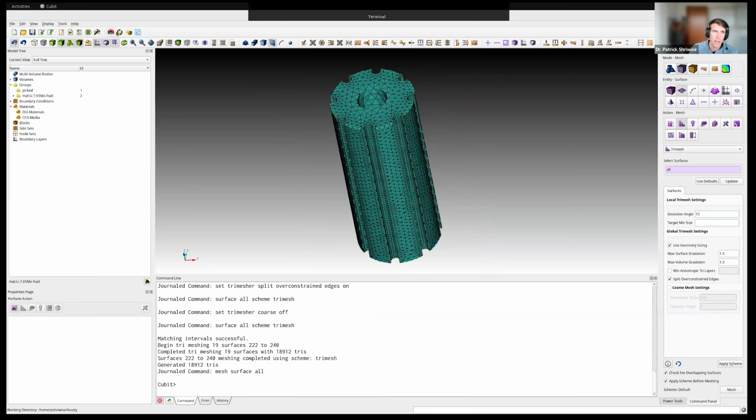And so what we've added is a DAGMC toolbar. Up here, this toolbar adds a few different buttons into Cubit. This is something that needs to be added on to Cubit when you download and install it. There's a package that will provide that, which includes instructions for that, and it's relatively straightforward and can be done almost entirely through the GUI.